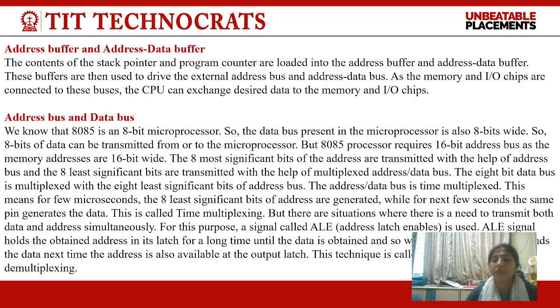This is called time multiplexing, but there are situations where there is no need to transmit both data and address simultaneously. For this purpose, the ALE signal is used. ALE is address latch enable, and it is used to demultiplex the address and data buffer.